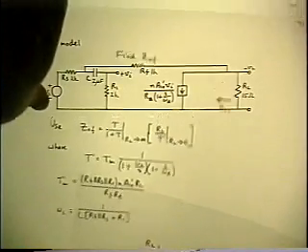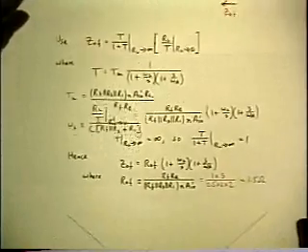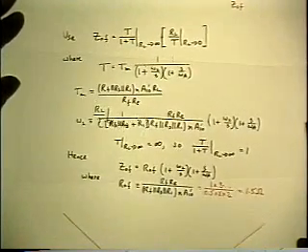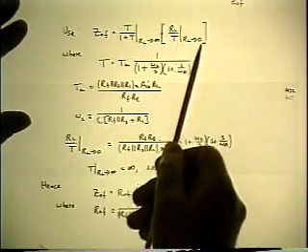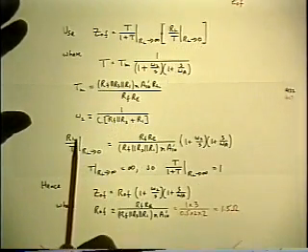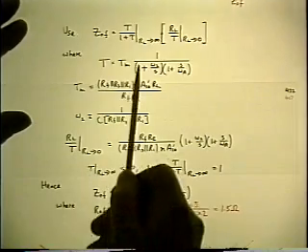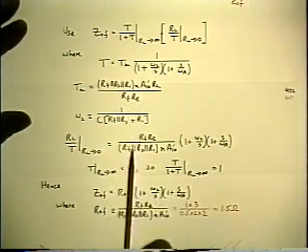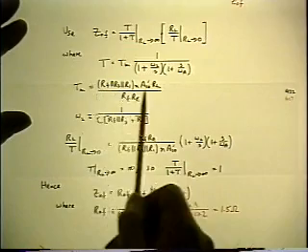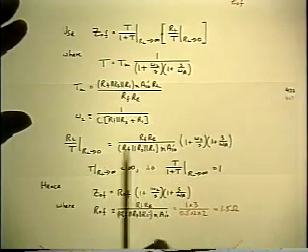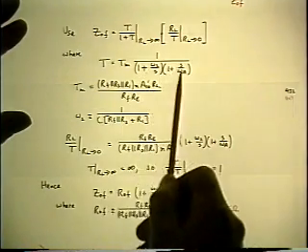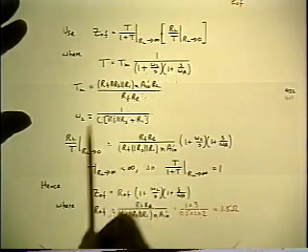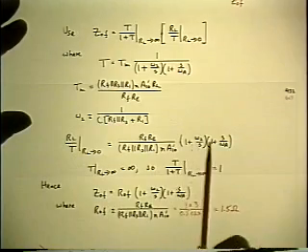So let's evaluate the limit with RL going to 0. So I have to take RL over T. So that's RL over Tm. And the Tm is proportional to RL, so it will cancel. And then I have the 2 corner frequencies for the T, and the 2 poles of T will be zeros of this function.